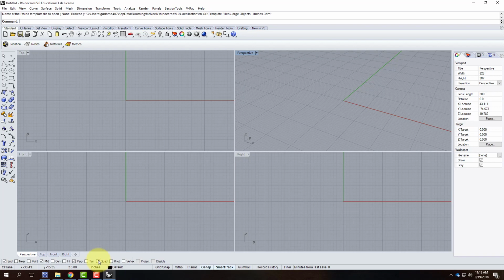So from here, we're going to go ahead and draw the shape right next to step 1. It's a 13-inch line with a 2-inch by 2-inch arc, or 2-inch radius arc. And so we need to start by creating that in the first place. There are, of course, many ways of drawing the arc, drawing the line, and creating the shape. I'm going to go ahead and do it the way I would do it. It doesn't mean it's the right way or the wrong way.